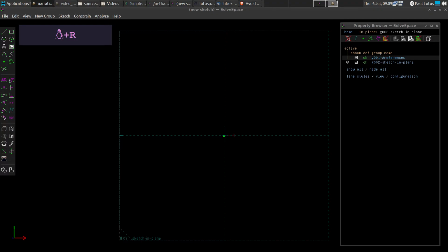There are two more extrusion commands to cover. These can be used to create duplicates of either sketches or previously created 3D extrusions. One of the commands creates a linear array of duplicates. The other creates duplicates on a chosen rotation axis. And they're right here, these two. This is the rotation axis command, and this is the linear command.